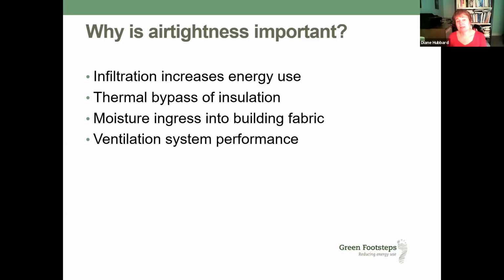Another thing to bear in mind is that air tightness could affect the performance of ventilation systems. So particularly where you're looking at maybe mechanical ventilation with heat recovery, which is being put into an awful lot of retrofits, you may find that if the building is too leaky, there'll be two consequences. One is that the air movement that's planned really doesn't happen in reality.